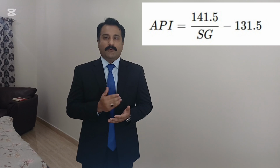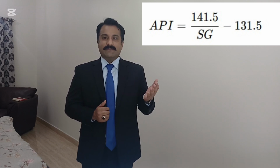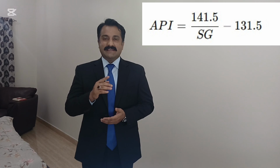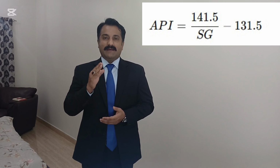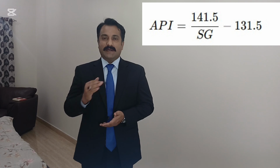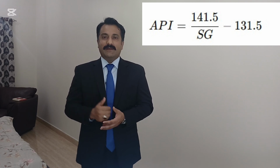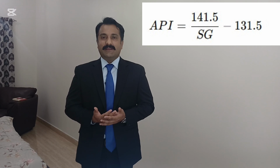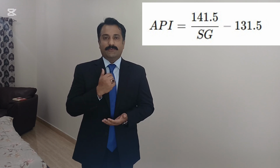Third one is oil API gravity. API gravity measures how heavy or light oil is as compared to water. The formula is API degree is equal to 141.5 upon specific gravity minus 131.5. We can calculate API gravity of any crude through this formula.